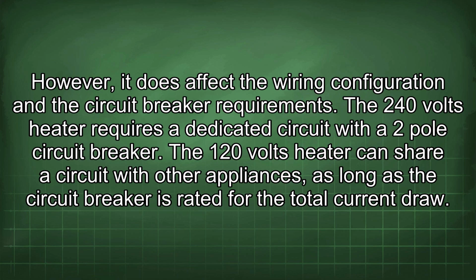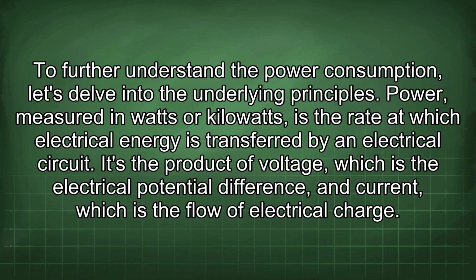However, it does affect the wiring configuration and the circuit breaker requirements. The 240 volts heater requires a dedicated circuit with a 2-pole circuit breaker. The 120 volts heater can share a circuit with other appliances, as long as the circuit breaker is rated for the total current draw. To further understand the power consumption, let's delve into the underlying principles.